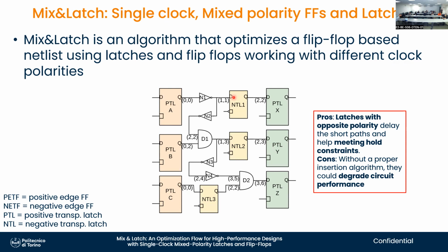Anyway, inserting buffers on the clock, tuning the delays on the clock. We are exploiting, in some places, insertion of maybe a couple of inverters or doing routing a little bit longer to slow down some paths. So we are still exploiting that, which is an inherent capability of the layout tools and the logic synthesis tools that we're using. And in fact, the best results are obtained, thank you for the excellent question, when